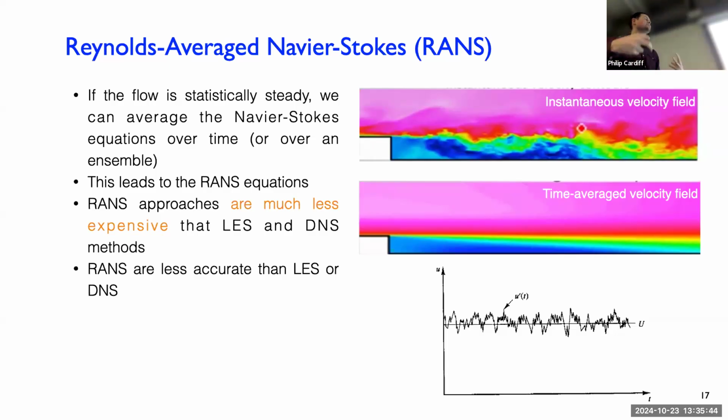So RANS gives you mean quantities. And by mean, we can consider it to be time average, or another perspective is what's called ensemble average. So imagine you did 100 experiments that are all the same. You do a wind tunnel downstairs, and then you just say after 100 seconds, I will measure the drag at that exact moment. And then you do that with 100 experiments. So you get some random variation between all of them, and you'll just define the mean across all your experiments. So an ensemble is a bunch of experiments. So you can define the average across experiments that varies in time as well. So you could have 100 experiments and just take the average at each time, and that will give a time varying curve that's smooth. It's the average across the ensemble. So there's just two perspectives.